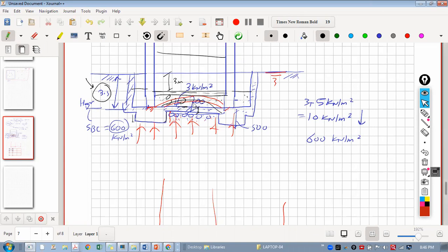Unless there is really an issue of the uplift pressure. If this is giving so much heavy steel and concrete, then your choice may be good at that moment. Sir, in PEB structure, many columns are uplifted, if columns are at longer spans. Right, in that case, yes, your choice is good.